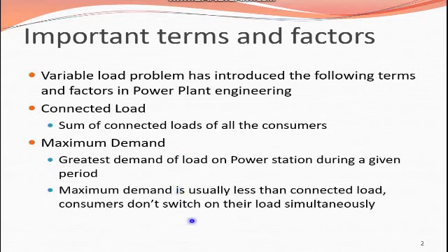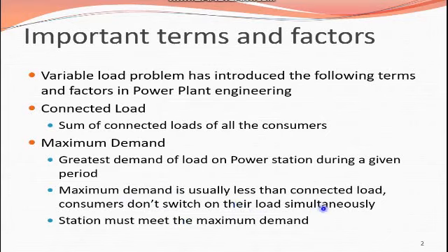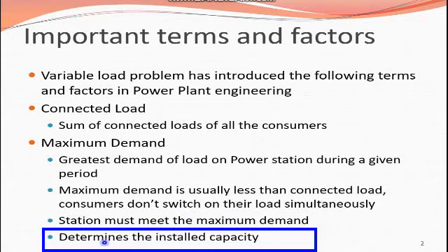The maximum demand is usually less than the connected load. Consumers don't switch on their load simultaneously. The station must meet the maximum demand, and most importantly, it determines the installed capacity.